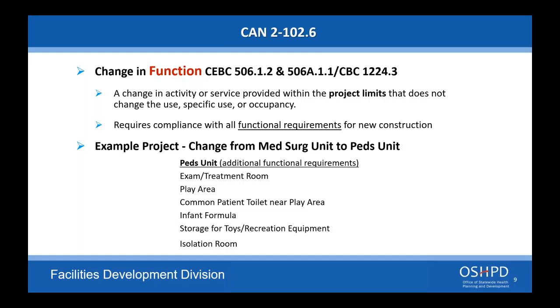Again, there is a requirement to balance the air that you're serving. Now, it's going to depend a lot on the area being served and what functions are in there. If it's an OR, it's going to be a way different requirement than if it's administrative. There are actually some clarifying statements in the narrative in the code for when it would apply to rebalance. But you need to expect there's a certain level of rebalancing when you put in a new unit.